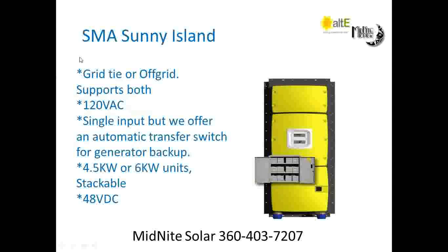So AC coupled, I didn't mention it earlier, but there's another feature of AC coupling that most manufacturers suffer from, and that is capacity. So say you have a 4 kW grid tie system, you need a 4 kW battery-based inverter. That is a true statement for everybody's inverter except for SMA's Sunny Island. The Sunny Island is capable of about a 2-to-1 ratio. So if you had a 6 or 8 kW or say 12 kW grid tie system, you could put it all on a single Sunny Island.